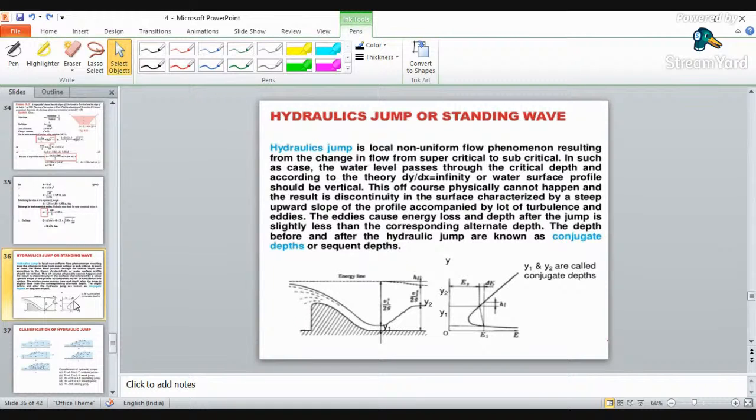Okay. So a hydraulic jump is formed when high velocity liquid is discharged into a zone of lower velocity, creating an abrupt increase in the depth. Hence, we can dissipate a huge amount of energy. This energy is nothing but a conversion of potential energy into kinetic energy, with some energy loss in the form of friction, turbulence or eddy formation, heat or noise. Okay.